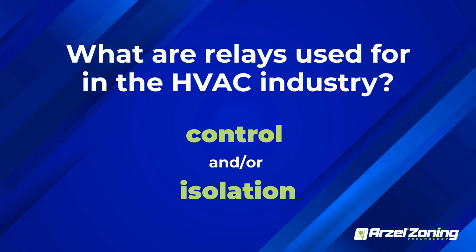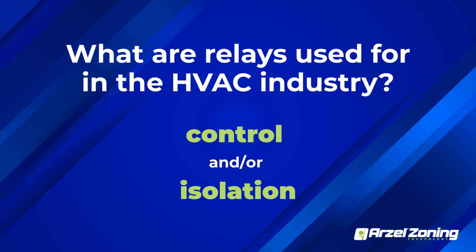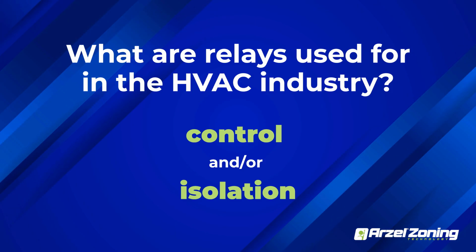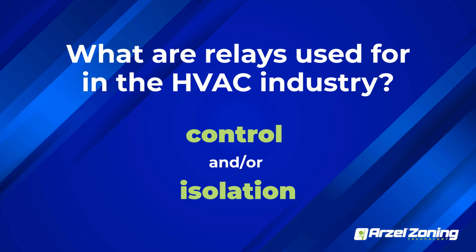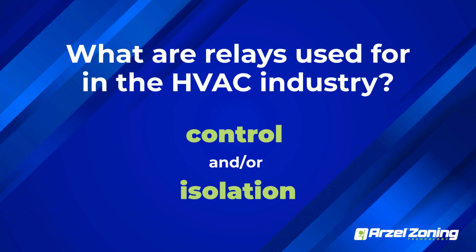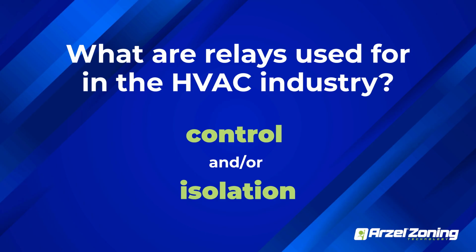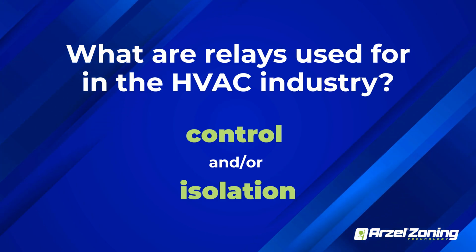If you tried to have, let's say, 4 thermostats on your furnace transformer and then power the zoning board with that as well, you'd burn out your furnace transformer before too long. It's just not designed for that current. So sometimes we need multiple transformers to provide additional energy, additional load rating. And that's where the isolation comes into play, because we don't want to tie 2 transformers together.